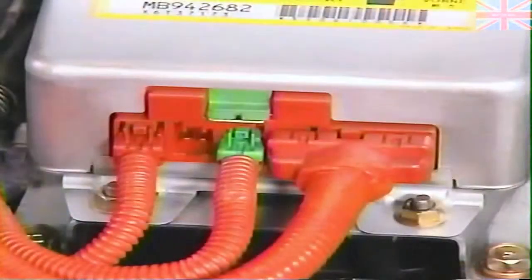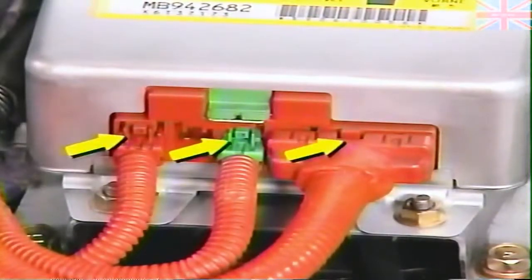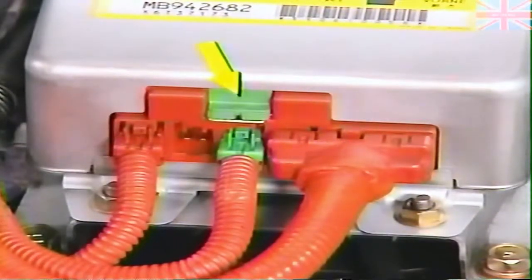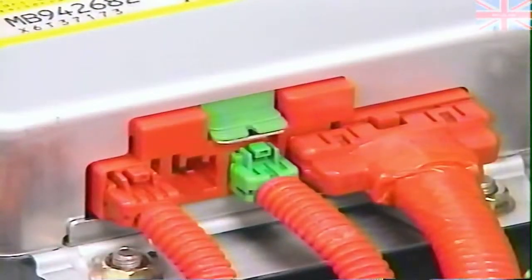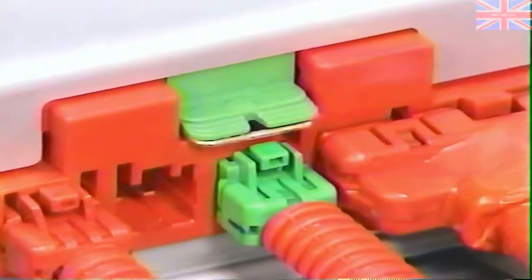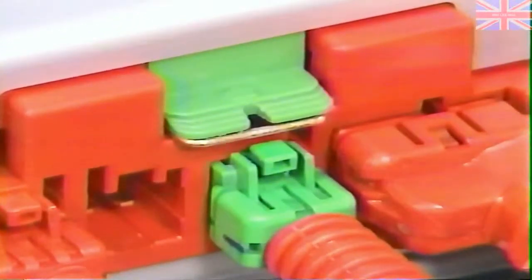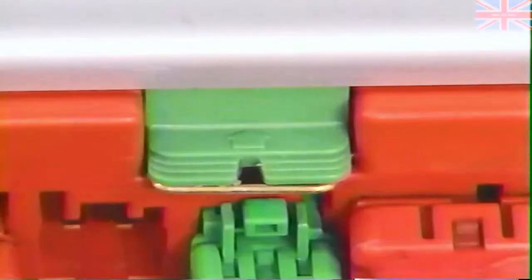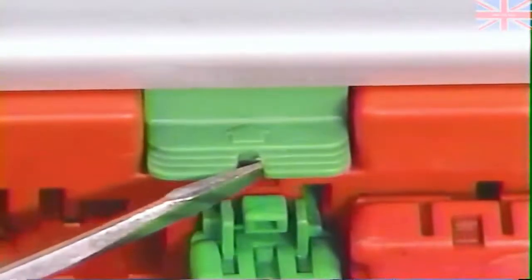Many of the diagnostic procedures require you to disconnect the SRS diagnostic unit. The SRS diagnostic unit has a double lock mechanism consisting of a primary lock on each connector and a secondary lock that retains all the connectors. The secondary lock has a spring below the green lock lever. For vehicles built after June 1993, a V-slot has been added to the secondary lock lever to aid in making contact with the connector lock spring. An arrow has also been added on the lock lever to indicate the direction to push the lock spring.